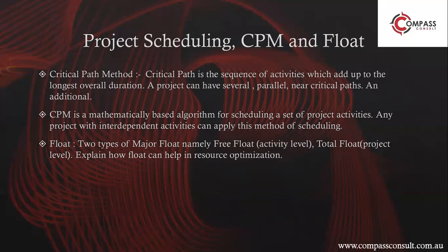We'll go to Primavera and see how a critical path is made, what makes a critical path, what is float, what is free float, what is total float, and how you can optimize the resources using the free float and the total float.